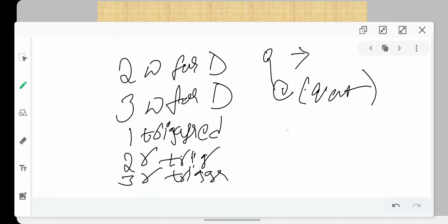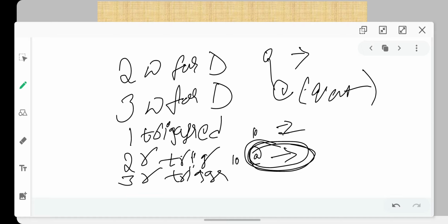But when the event is triggered at, for example, 10 time units, and your @ statement also happens at 10 time units, this is not going to catch your trigger. So this is the disadvantage of using the @ triggering statement. This type of wait statement is a disadvantage in your events.